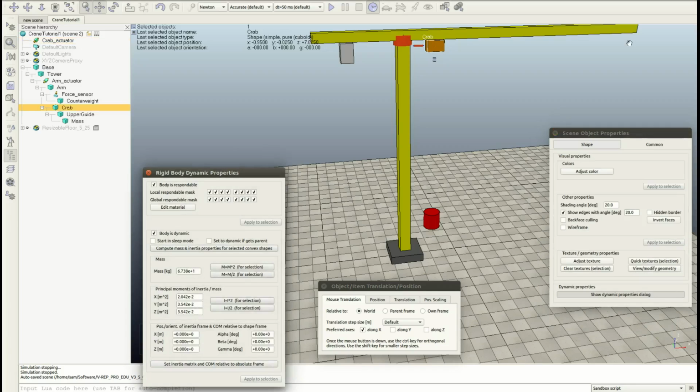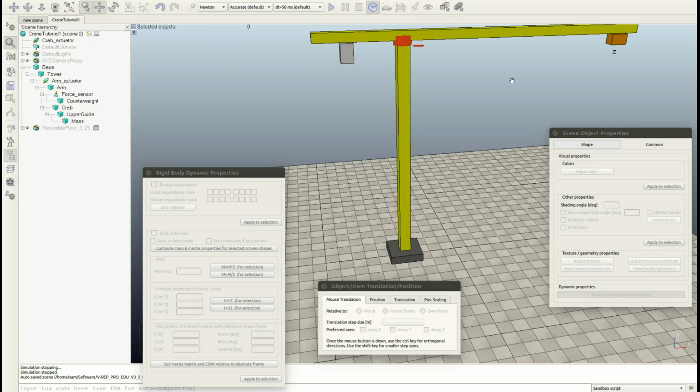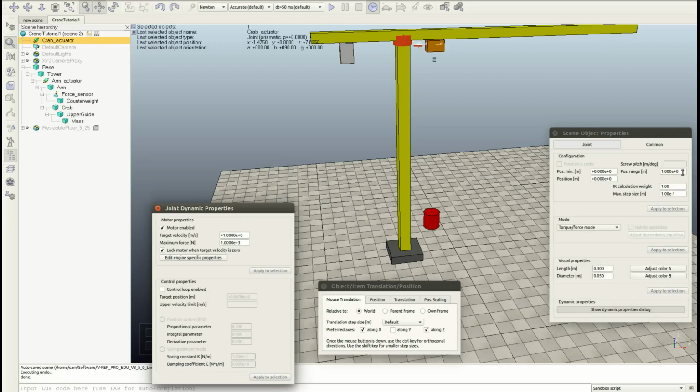So how do we find out this length? If you have a drawing, you could measure it, but I pick this, move it along X, and you see on the right there is a plus 0, 0, 0, 0, which is the translation. And you see now we are at 6.5, which is totally fine. So our range will be 6.5. Let me undo this. So let's go ahead here and say the range is 6.5.